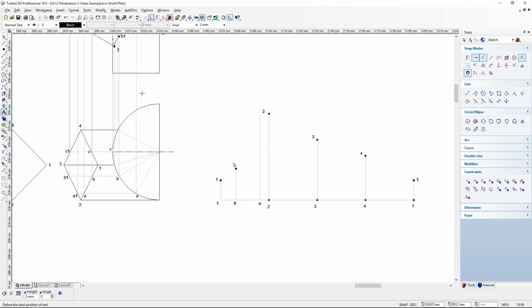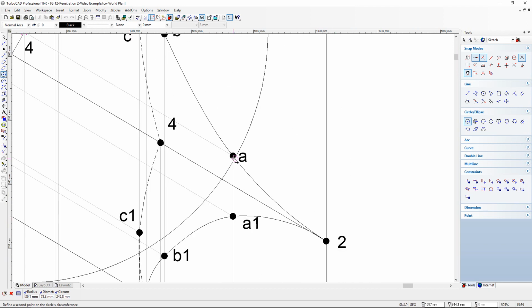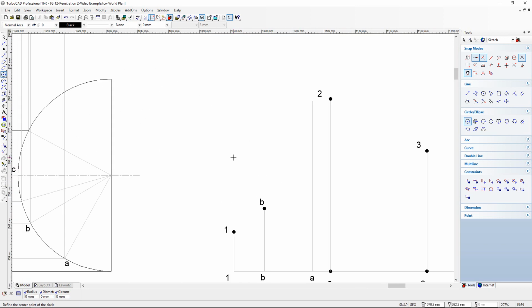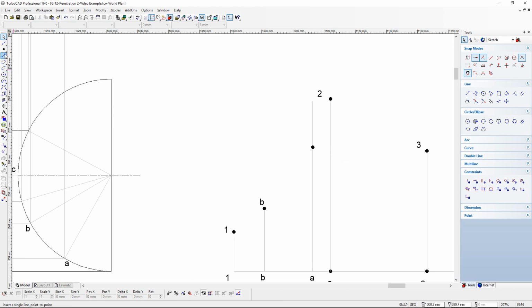Now that I have that, I just need to do A as well. So I go back to my front view. I measure from the baseline A to the height of the penetration, and that will be 38.7. So from A is tab 38.7, and then I can place my dot there and clear my measuring tool and label that number there, or that dot, as letter A. Good. And then I will shorten the line.